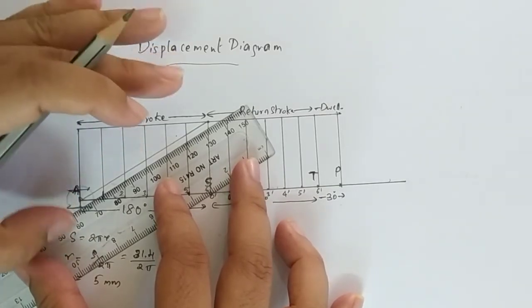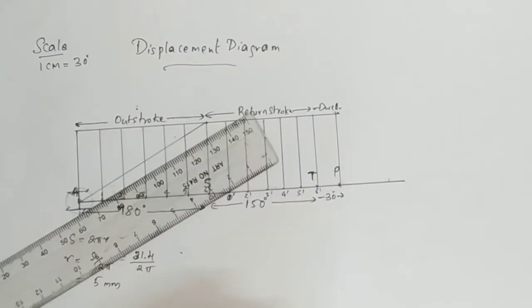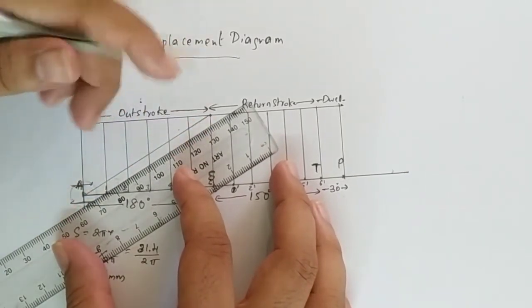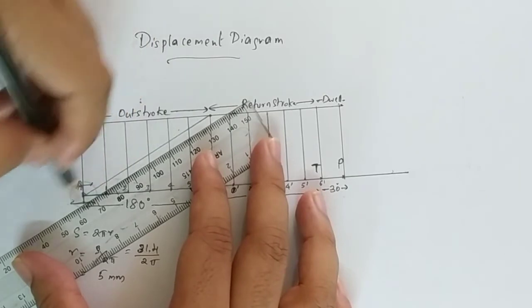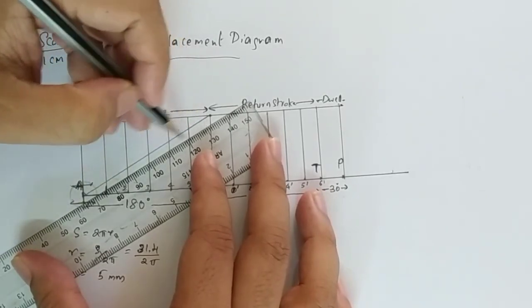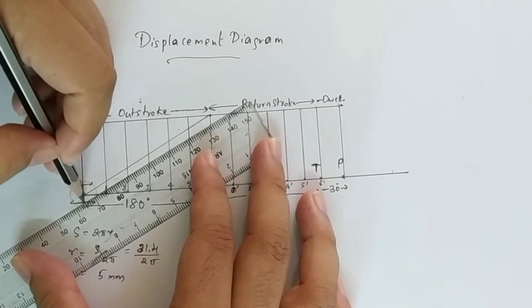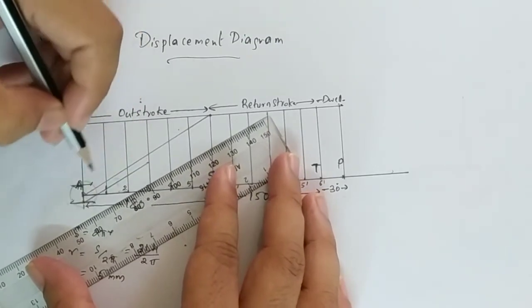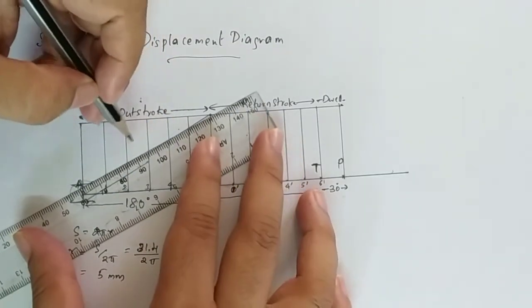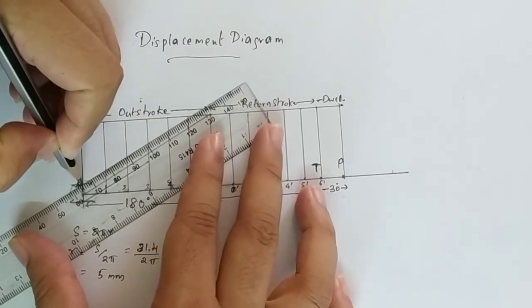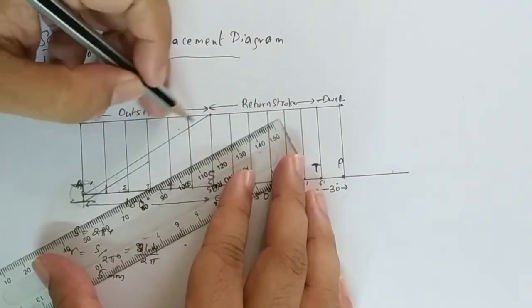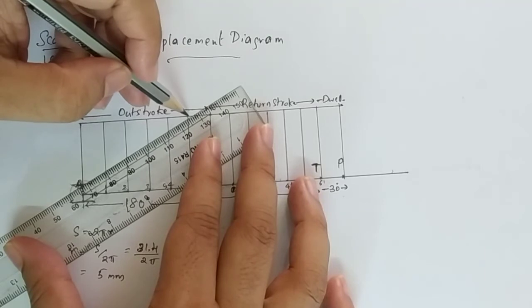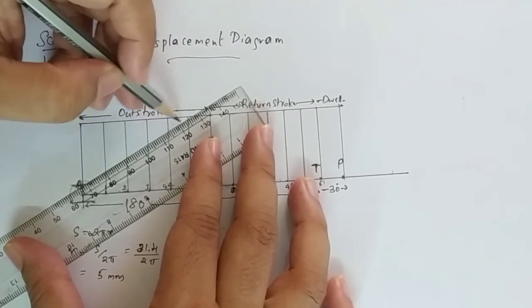Here I am just taking a rough parallel line, but actually you can use a roller scale, roll it down and get the parallel line. But here as of now, if you take it like this, no problem. When you draw, make sure this below line will be used only up to these 3 points. Up to this, if you draw, that is enough. But the above line will be used for the top value. So if you start from here also, no problem. Make sure the line you are going to draw is parallel to the center line. I am taking some approximation here, but in your case you have to take the actual by using a roller scale.